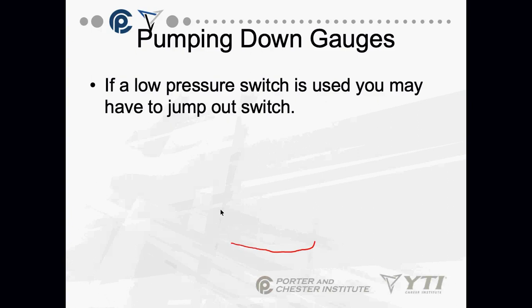Now, do I still have refrigerant in these hoses? Yes, because I have my gauges here. There's a low side and a high side. The low side is still connected to the system in the suction line. The high side gauge hose you're holding in your hand has that low loss fitting on the end of it. The low-loss fitting prevents the refrigerant from escaping into the air. So all that liquid refrigerant is still in that gauge hose. My low side is connected.